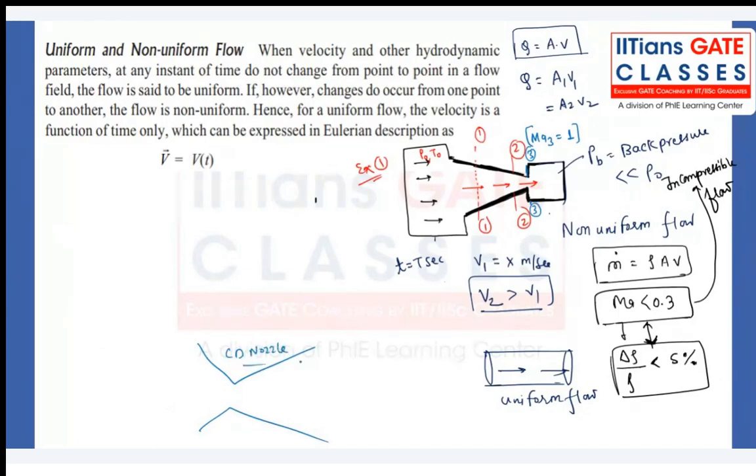That's why you cannot attain Mach number more than 1 only with the help of a nozzle, right? Being a gas dynamics engineer, you should know why the Mach number cannot be greater than 1. Have you ever thought? Even though you reduce the back pressure, you can increase the mass flow rate to the maximum, let it be a constant maximum mass flow rate, but still Mach number cannot be more than 1. Anybody know the reason for that?